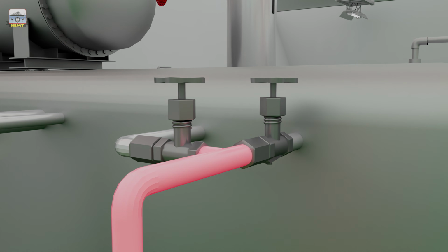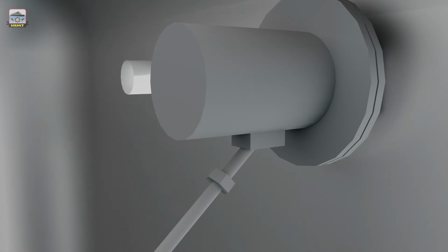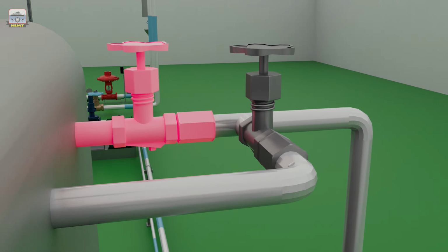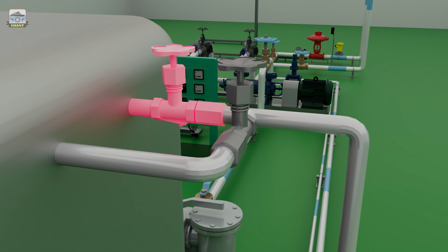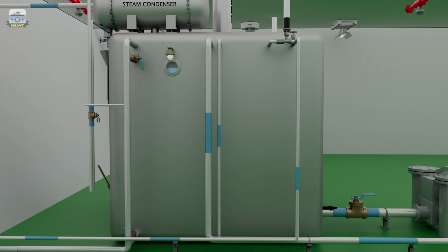The filling can be done automatically through this branch pipeline, which is fitted with a float valve, or manually through this branch line. Maintaining the proper level of water in the hot well is critical for the uninterrupted operation of the steam plant.